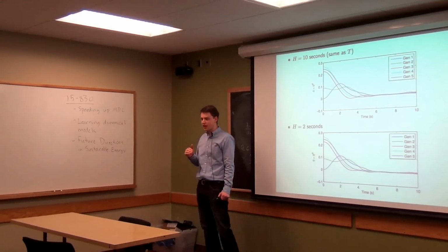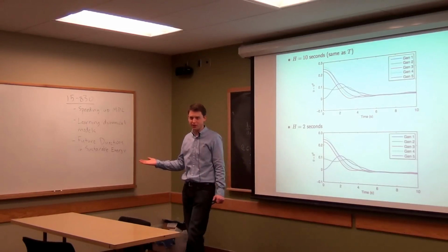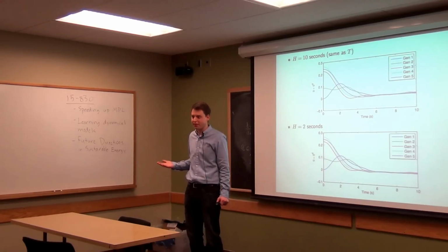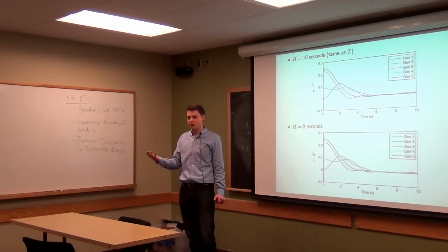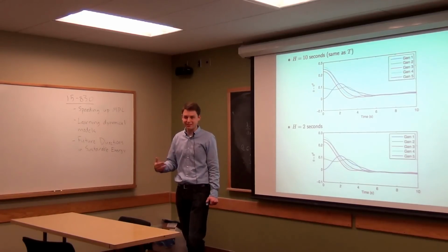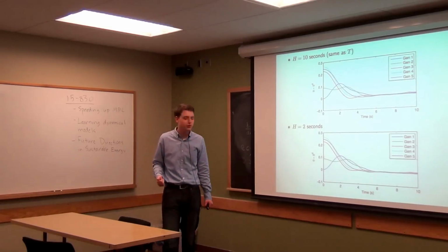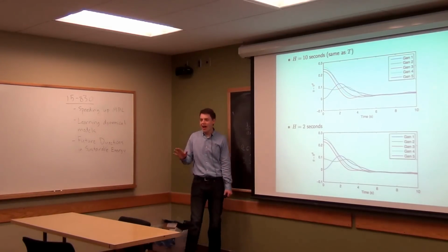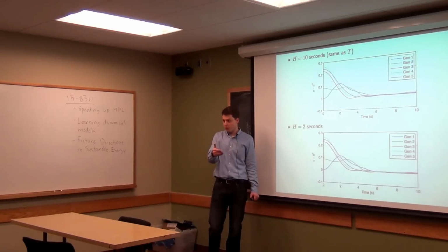Then it turns out that anything you did with your control wouldn't have any effect on your cost, right? Because you can't actually affect the state at all. You're not going to even think about the next time step when you're computing your cost. And so you'll just use the minimum possible control, which is basically 0. And you'll just keep doing that. You'll just keep saying 0, 0. That looks good because I can't really do anything, so I'll just keep picking 0 as my control. And while that obviously is an extreme case, that same idea manifests itself when you pick too short a time horizon.